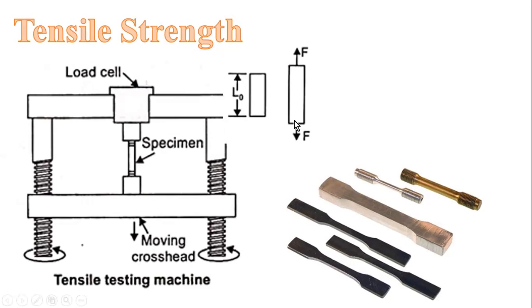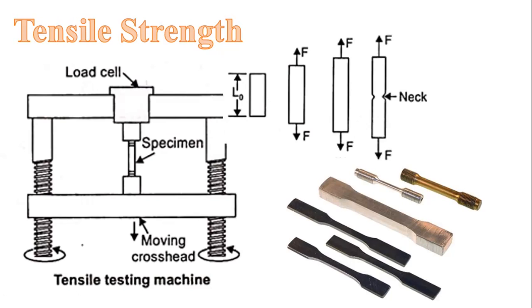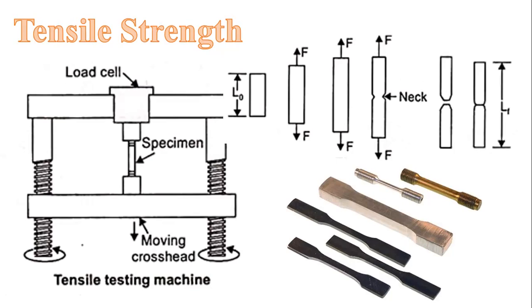And you can see here the elongation, because this is bigger than this one. The third is that you continue the elongation until you reach a maximum load. The fourth is that the necking begins and the load begins to decrease. This is the neck, in which you start seeing that it is going to break. The fifth is the total fracture of the specimen, and the sixth is the final length that you can measure.